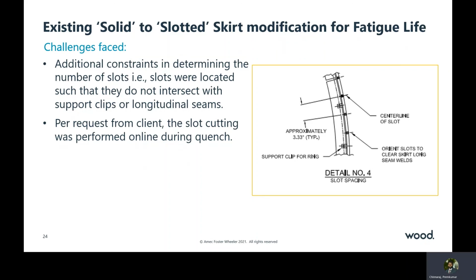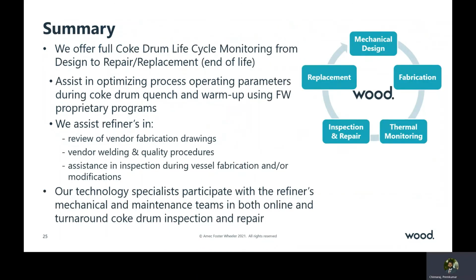In the end, we provided support to the field and coordinated with the fabricator during the slot cutting process to meet the quality requirements specified for this slotted skirt design. As discussed in these case studies, it is evident that addressing fatigue only during the design phase is not adequate. Coordinating with the fabricator to meet the design requirements by reviewing fabrication drawings, weld and quality procedures is necessary. After startup, thermal monitoring and operational optimization using our proprietary programs are critical. Providing enough inspection windows to monitor the critical areas of the drum and planning maintenance repairs are important to avoid